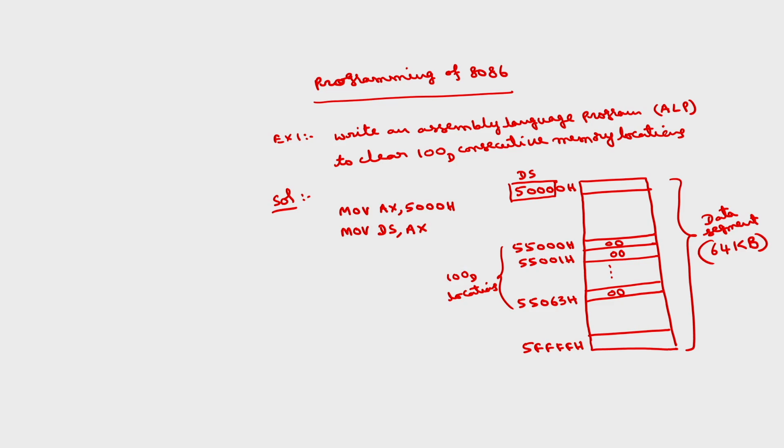We cannot take this data or address directly into the segment register. Now, the data segment will point to this, and what is the offset from where we have to load? The offset from here to here will be 5000. This is also called the effective address. I can take this effective address into any other register, a base register or index register. So, I will write LEA, load effective address, taking the BX register to hold this. What is that address? 5000H.